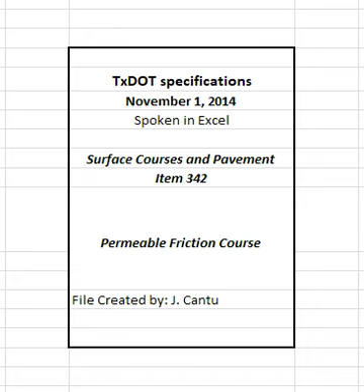4.4.2.1.9 Trial batch production. Provide a plant-produced trial batch upon receiving conditional approval of JMF1 and authorization to produce a trial batch including the WMA additive or process, if applicable, for verification testing of JMF1 and development of JMF2. Produce a trial batch mixture that meets the requirements in Table 2 and Table 5. The engineer may accept test results from recent production of the same mixture instead of a new trial batch.